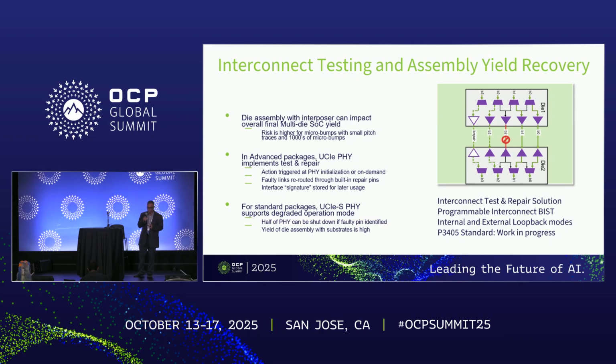And then finally, the interconnect test is important because we are talking about hybrid bonds, 2 micrometer pitch. As I mentioned earlier, there are definitely going to be big particles causing shorts, and shorts are more common than opens, but we need to fix and repair this interconnection. So UCI has 3 standards anyway: A for advanced packaging, S for standard packaging, and finally it also has the standard for 3D. So it uses the 1838 standard.